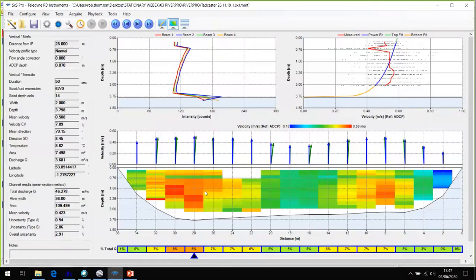I will often say in my ADCP training, if you see something that looks bad, it probably is bad. And hopefully your understanding of how a river flows leads you to understand that a big, uniformly green stripe surrounded by varying degrees of much faster water immediately above and immediately below can't be right, and it isn't right. And as Ian's just pointed out, we've known about it for quite some time, and RDI just haven't fixed it.